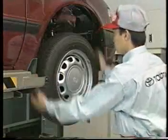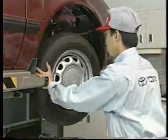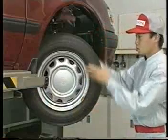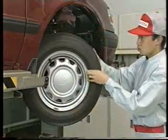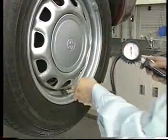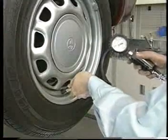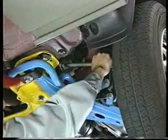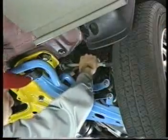Now let's see the actual wheel alignment procedure. First, check the following points. Check the tires for improper size, wear, deformation, and improper inflation. Check suspension and steering linkage for looseness.